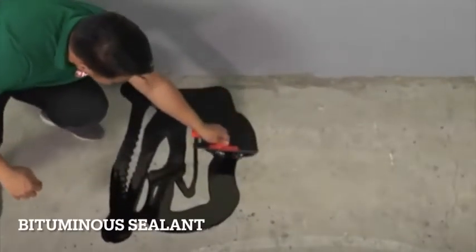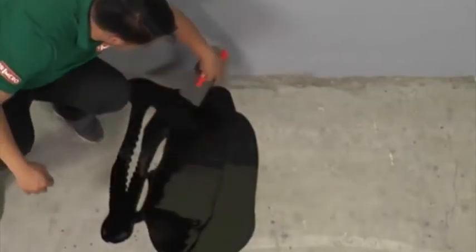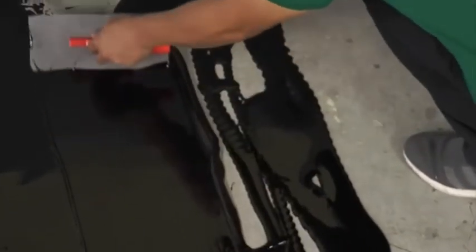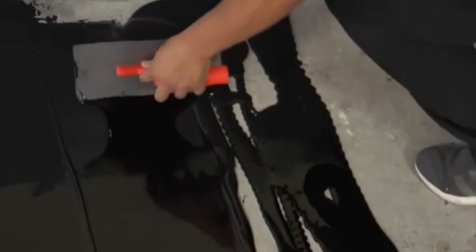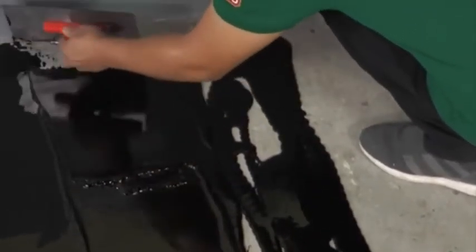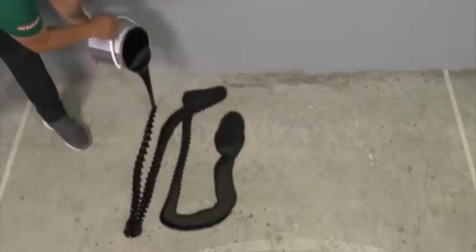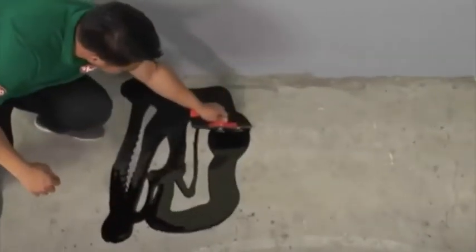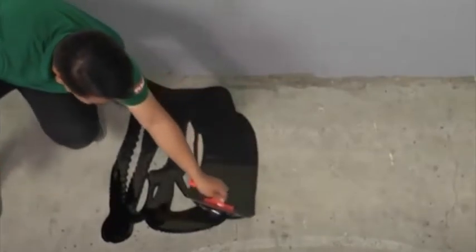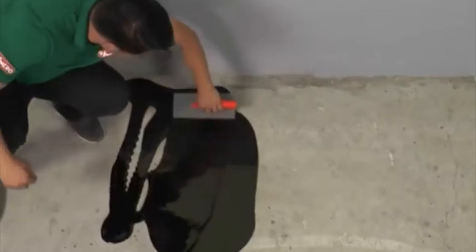Bituminous cement is a black substance available in solid, semi-solid, or liquid states at normal temperatures. It is composed of mixed indeterminate hydrocarbons, appreciably soluble only in carbon disulfide or other volatile liquid hydrocarbon. Bituminous cement is used for sealing built-up roofing and joints and cracks of concrete pavements.